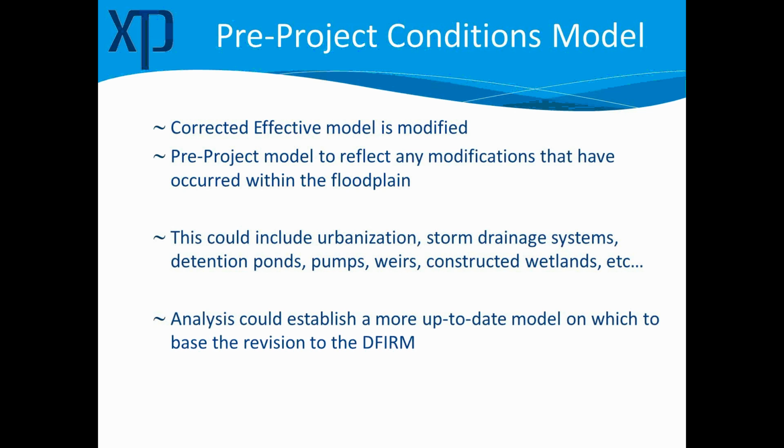The NFIP, and all of the guidelines and specs, speak to accounting for urbanization, but we really have never done it, in my opinion, with the traditional models, for a lot of reasons, I think. One, they were separate models. Because it wasn't fully dynamic, it didn't account for the process. But interestingly enough, sometimes the results of the floodplain delineation look very similar, but I think that may not necessarily always help in floodplain management needs. That may be just an irony of the modeling there.